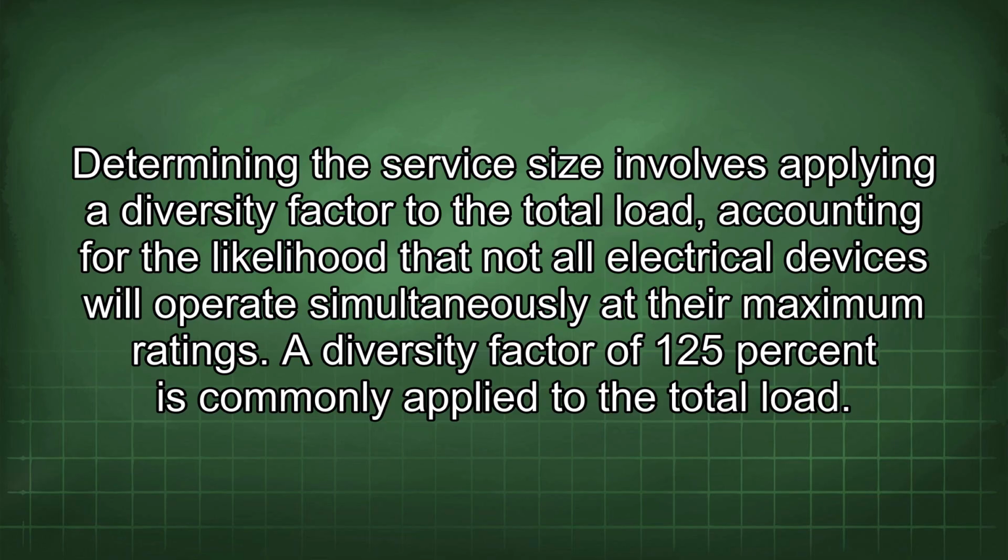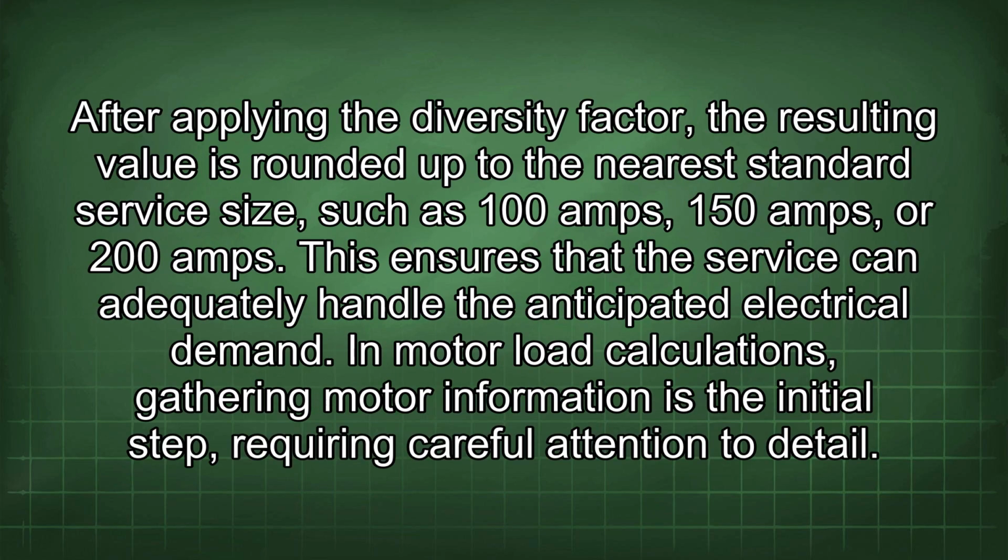Determining the service size involves applying a diversity factor to the total load, accounting for the likelihood that not all electrical devices will operate simultaneously at their maximum rating. A diversity factor of 125% is commonly applied to the total load. After applying the diversity factor, the resulting value is rounded up to the nearest standard service size, such as 100 amps, 150 amps, or 200 amps. This ensures that the service can adequately handle the anticipated electrical demand.